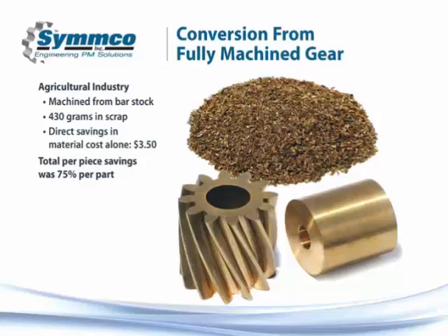They moved to the PM gear, and it saved a tremendous amount initially. In fact, it saved 430 grams, nearly 1 pound, that was absolutely cut off and fell to the floor around the machinist, just total scrap. That alone was a $3.50 savings in the bronze material.